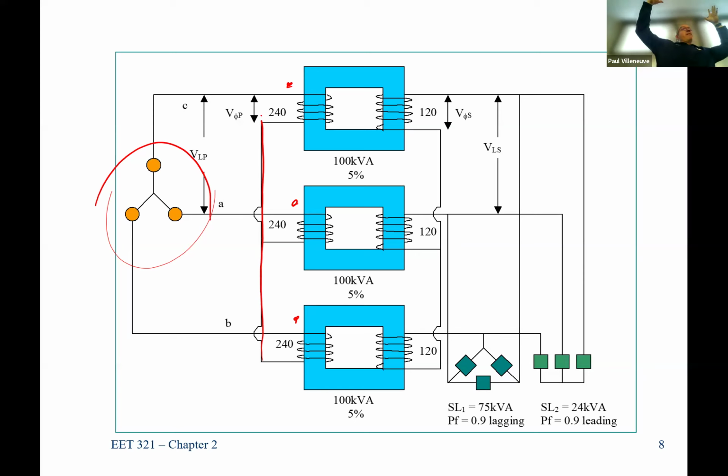And the reason they have three cans on a pole, not one can on a pole, is typically that it's much easier from a maintenance perspective. If I've got three transformers and one of them fails, it's a lot easier to change out one smaller transformer than one bigger transformer. So under really important, reliable conditions, or really big applications, it's always better to go with three single-phase transformers.